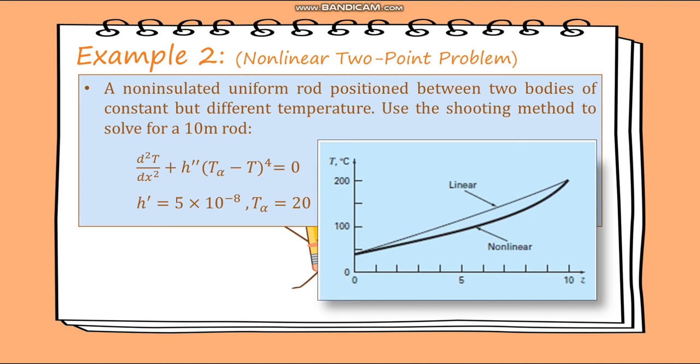The function integrated the equations based on an initial guess for z(0) and returned the temperature at x equals 10. The difference between this value and the goal of 200 was then placed in a spreadsheet cell. The Excel Solver was then invoked to adjust the value of z(0) until the difference was driven to 0.